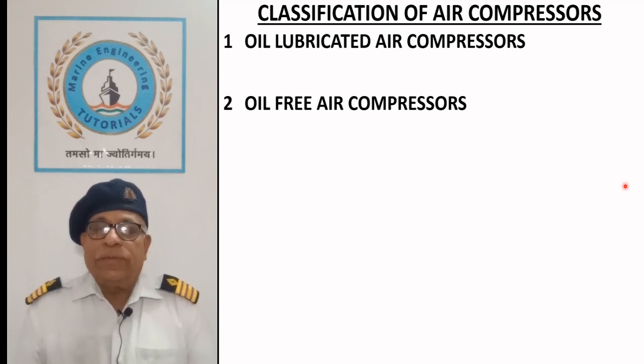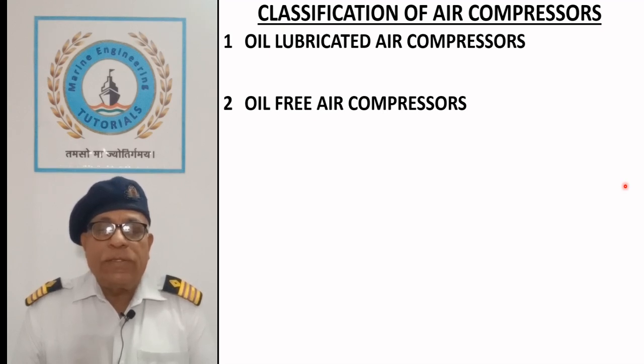Such compressors have dry crankcase and the main crankpin and gudgeon pin bearings are of ball or roller type, lubricated by grease. Split type crankweb is used for fitting and removal of crankpin bearing.